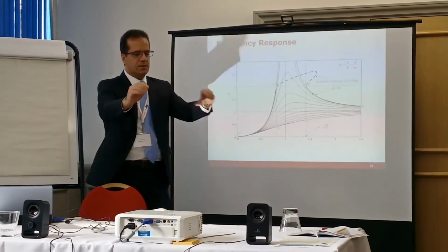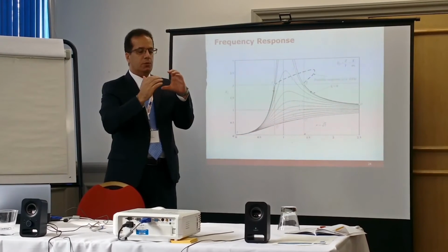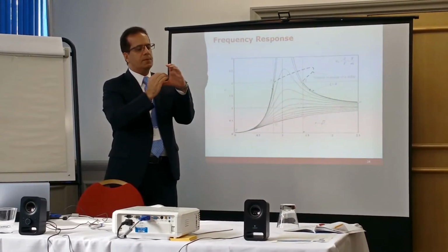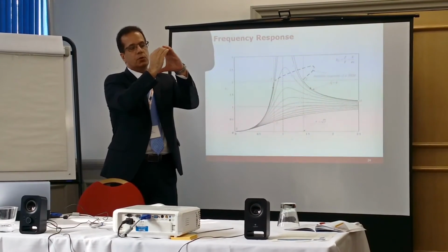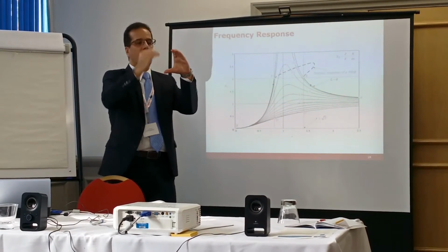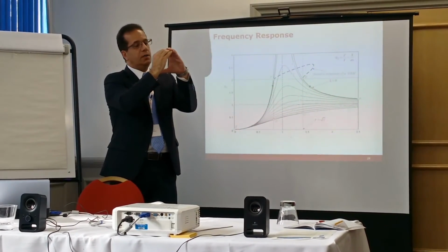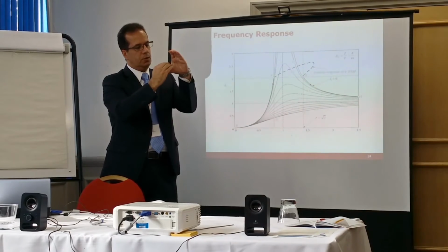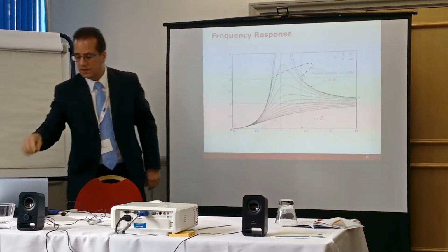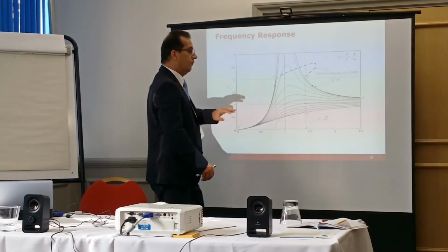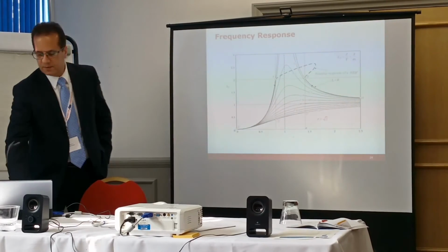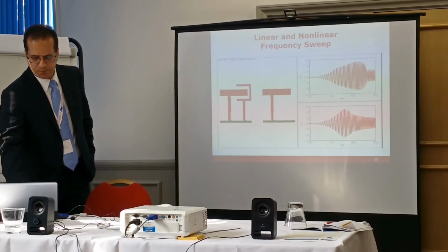Let's assume that the amplitude is high enough that we have engagement. Now at that frequency, what happens? We have this engagement, so two dampers, two springs, and then during one cycle of motion, we go from high damping to low damping, to high damping, back to low damping. So one cycle is a combination of low damping and high damping. It is not just on high damping. This affects the whole system.